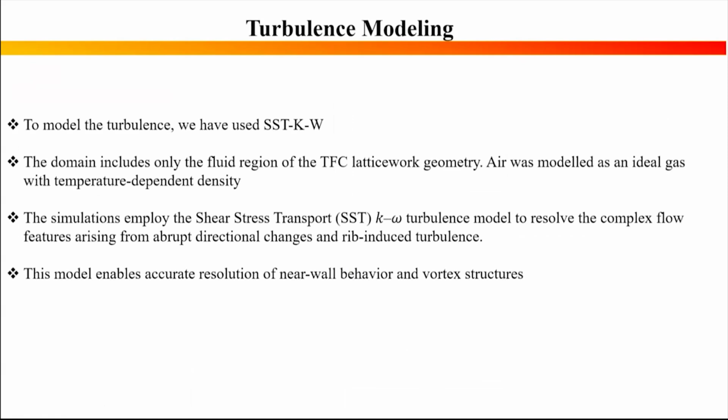Turbulence modeling. In turbulence modeling, we are going with the SST k-omega turbulence model to resolve the near-wall behavior of the fluid and to capture accurate vortex structure. A dedicated turbulence modeling demonstration tutorial is in the pipeline, which will be provided by our FOSSEE research assistant. So kindly stay tuned for that.